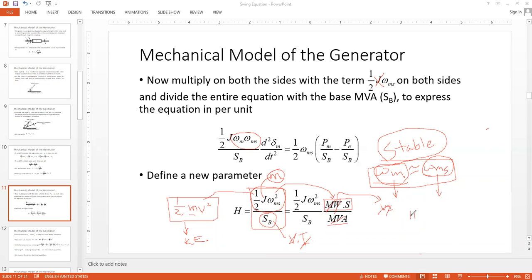Okay. So H is known as the per unit inertia constant. Although it is known as per unit, and as we know in a per unitized system these are actually unitless, or at best we can use per unit, PU, as their units, however there is a little deviation from that concept, because here the unit for H is seconds. So it is per unit inertia constant, but measured in seconds.